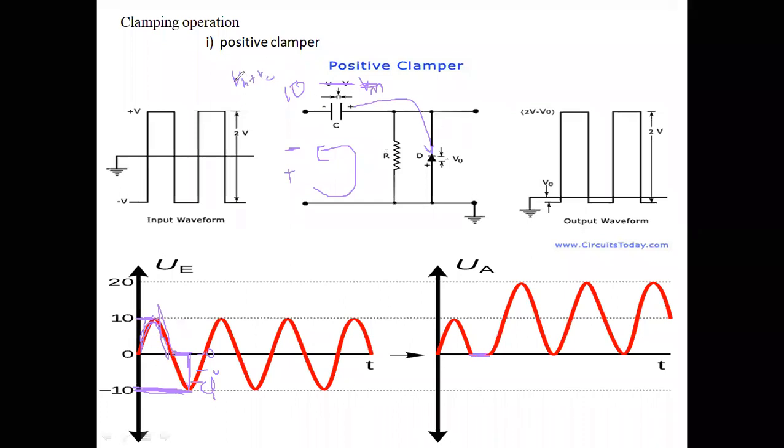Okay, Vin is at minus 9, this is at minus 10. Therefore, you may get the minus. This is a plus 10. The capacitor's positive terminal is connected at the output terminal. Therefore, this is at plus 10, and it is connected to minus 9 volts. Input voltage is minus 9 volts. Therefore, the resultant voltage is plus 1. Okay, plus 1 will occur here.